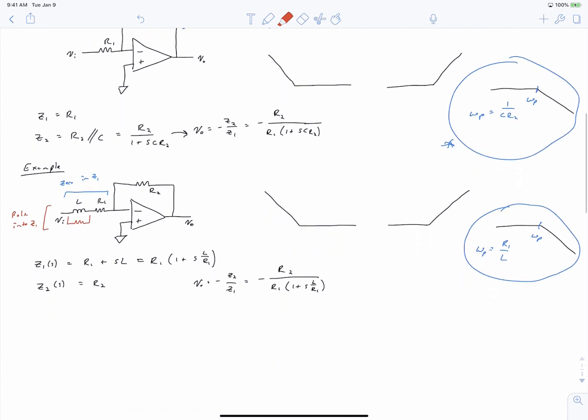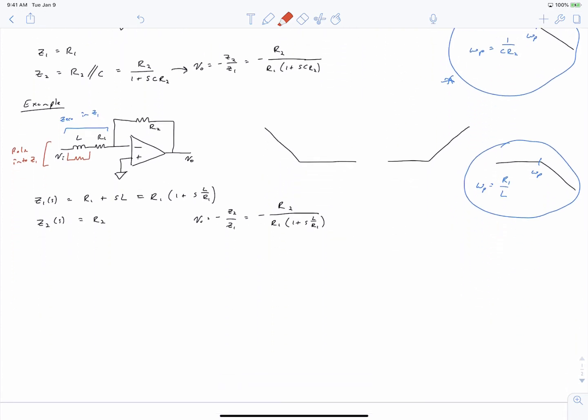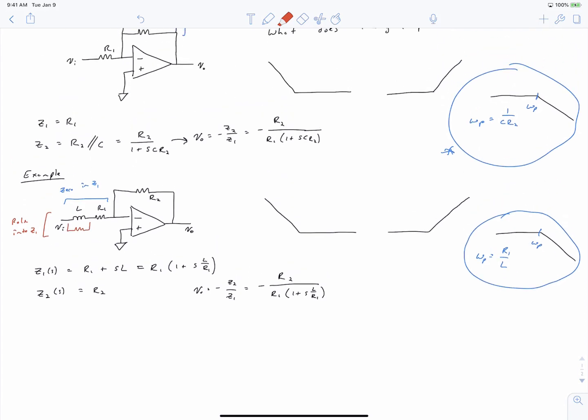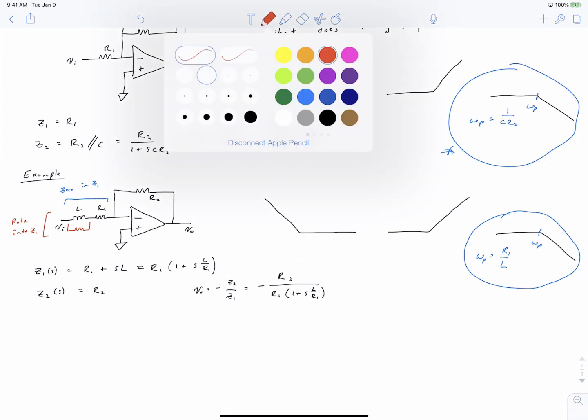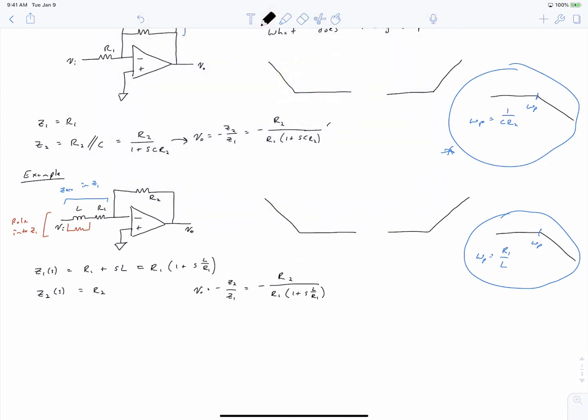So this all relates back to the transfer functions we've been working on building up so far. And we've commented now on how you can modify these impedance networks in order to realize a transfer function equation, in order to introduce zeros and poles into these expressions for your output voltage. And I apologize, both of these expressions should be multiplied by your input voltage, or what you could say instead is that it's Vout over VI, which is indeed a transfer function.